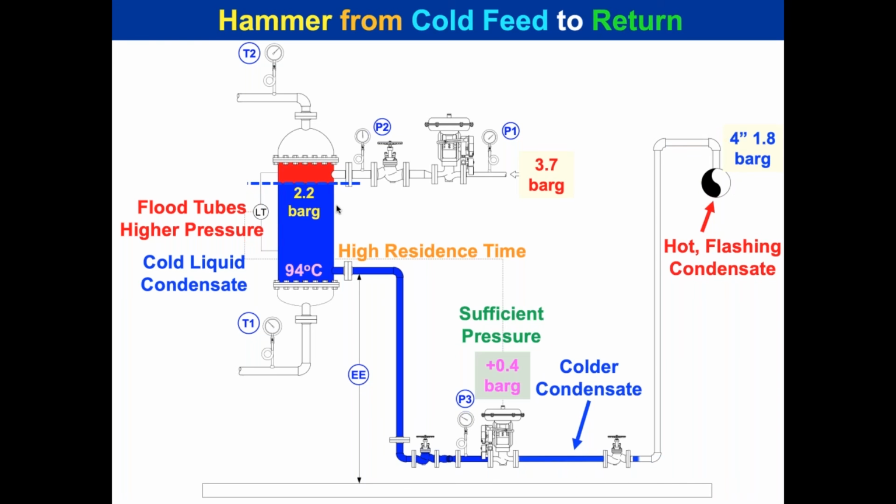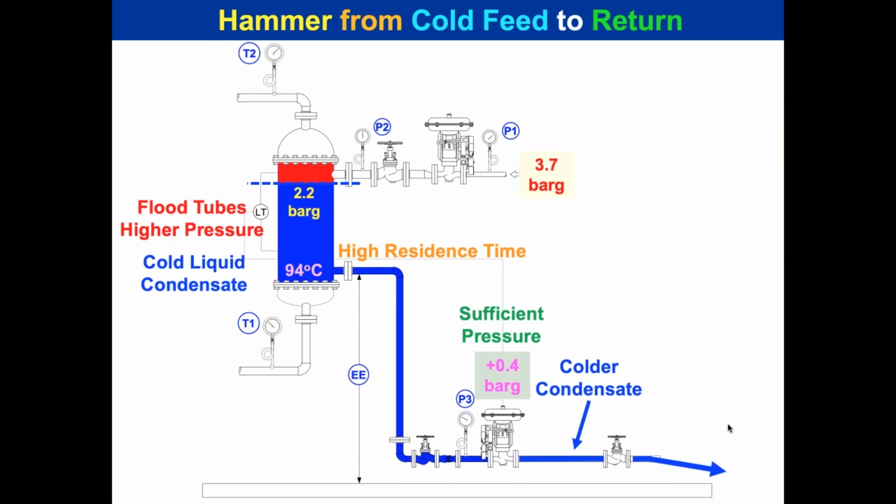What do you think is going to happen? That's what happens right there. So what do you think they had to do? Yep, they had to waste that condensate. And then the problem with it is they were really close to the flood line in that thermosiphon reboiler entry point. So they had all kinds of problems with that.